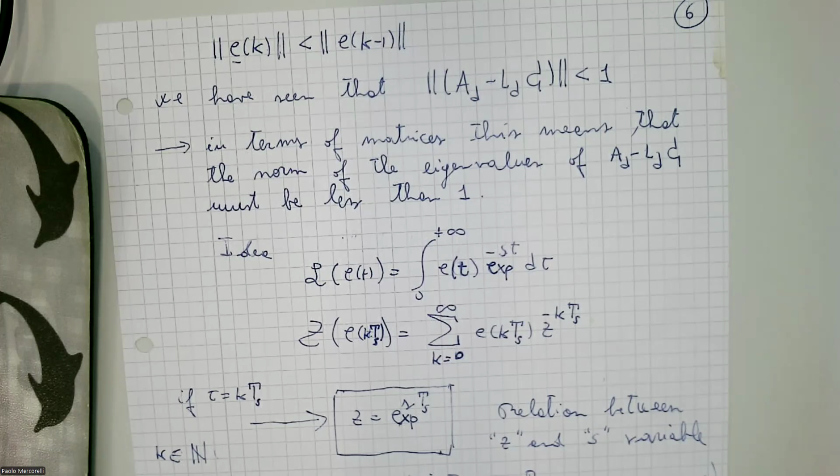It's not a suitable choice because of this reason, and because of other reasons, but the problem is sometimes TS is large because we have to put inside this TS many calculations, many algorithms, model predictive control or different algorithms. And this is running inside the TS. This means it's not always possible to reduce it. How much can I reduce?